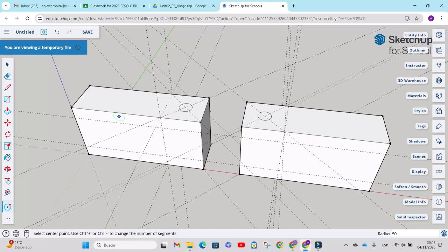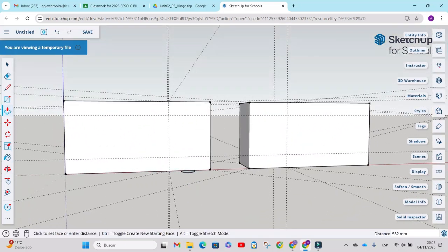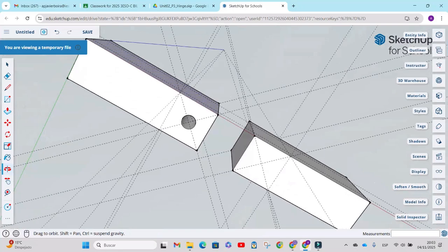That's it. Now we are going to make the hole, therefore we choose the push tool, we select the inner circle and we can even click on this line, which is the last. Here you can click when the point appears right there. See, now we have the hole.